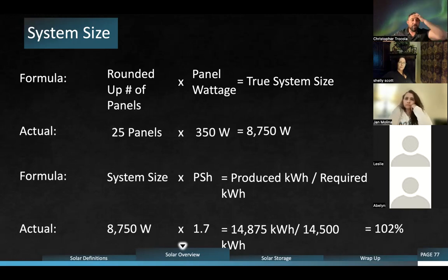Yep. So it was 13.6 kilowatts if it was still going to be her and her 2 other kids inside the house. Since it's just going to be her son in 3 years, it's going to take her 1.5 years to build the pool. She's not buying that electric car until after she's getting ready to move out. She's not even going to need all that. 10.4 kilowatts is all she's going to need for the pool, for her appliances, and for the 3 people, which means when it goes down to 1, he only needs an 8.4 kilowatt system.